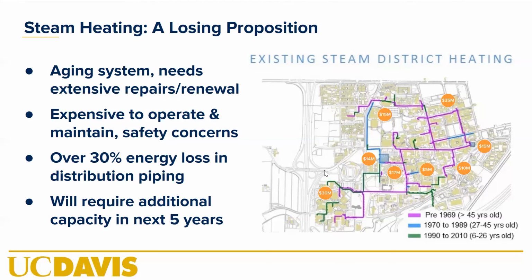For example, in the summer, we still are using heating in buildings based on the nature of these systems. They still need to have some zones with heating. There's also steam usage in buildings for various processes. And so the entire steam system, this 27 miles of pipe, has to stay energized with 350 degree steam. And when very few buildings are using it and the usage is low, you can imagine that the losses in those pipes are very high, that it's all condensing back into hot water and coming back to the plant without ever having done any heating out there. So could be very high losses.